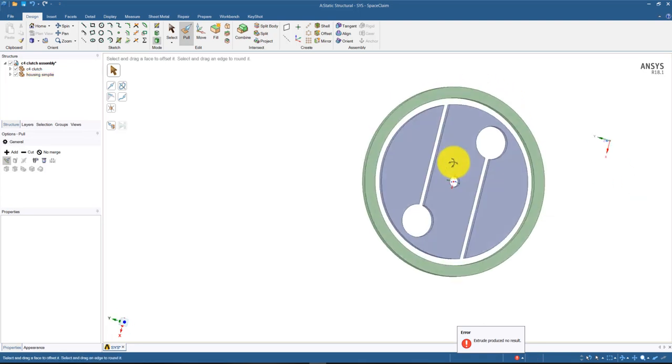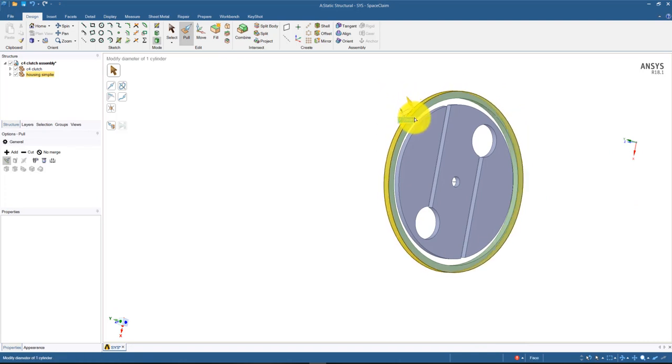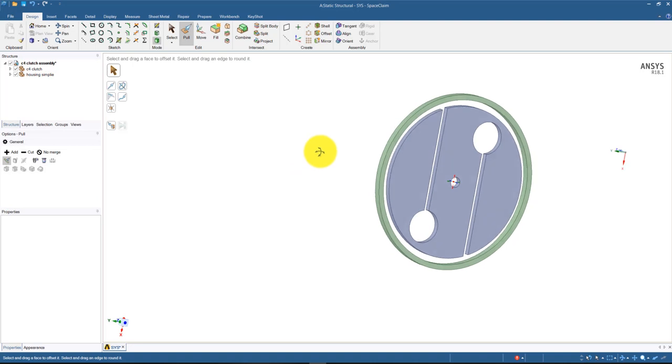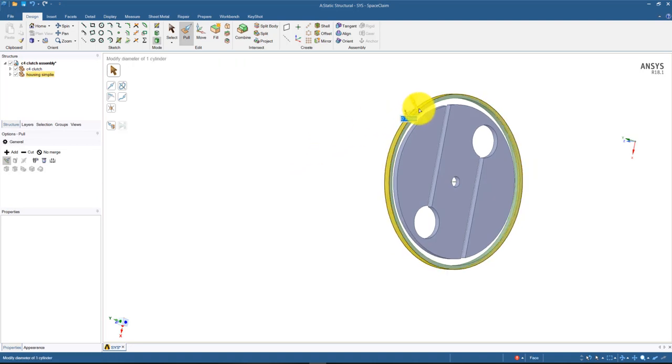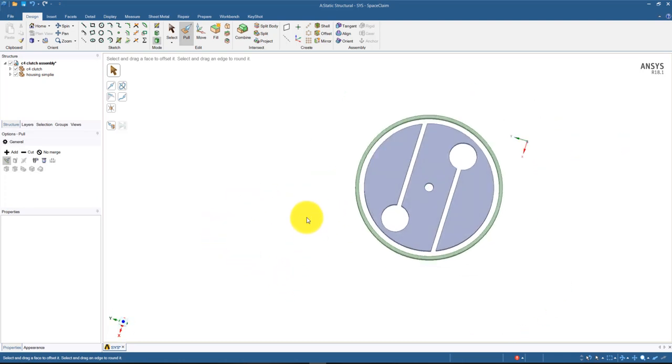Now I also don't need much difference between the inner and outer diameter, so I could narrow this down. Here I'm just simplifying the geometry. Exact dimensions aren't very critical on that OD. Now it'll mean less mesh I have to use in order to do the simulation.